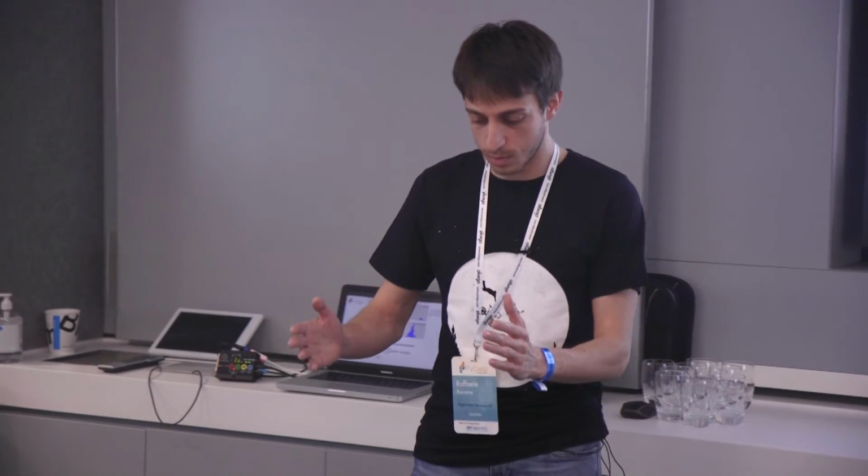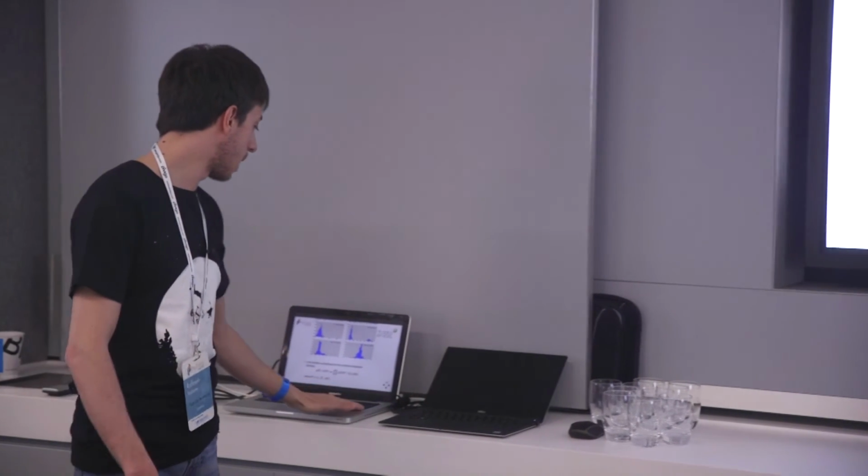Bayes' theorem is telling us that if I want to check the probability that a data point is the end of takeoff, I just have to compute this product. So the likelihood would be the end of takeoff given my parameters, and the prior will be given by our prior knowledge on the parameters, that is the time, the fuel flow, and DGT. And precisely, the likelihood will be inferred from our histogram.